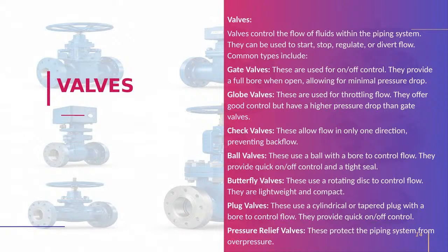Next is the ball valve, same as I explained before. Mostly ball valves and butterfly valves we will see for higher flow rates, like water and air, which handle the major flow. In those areas we will be using butterfly valves, and plug valves where tight shut off is required, where quick control is required.